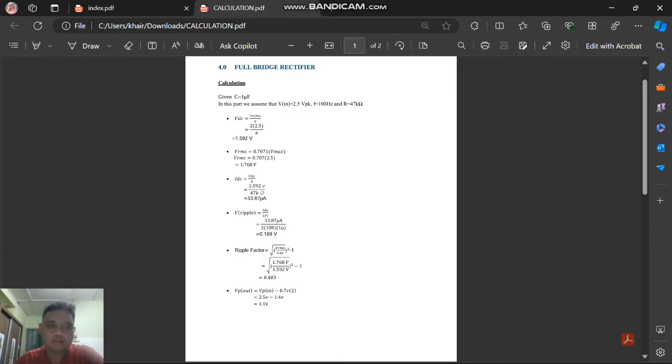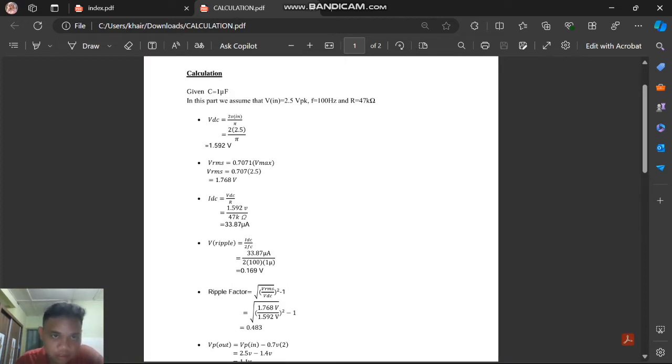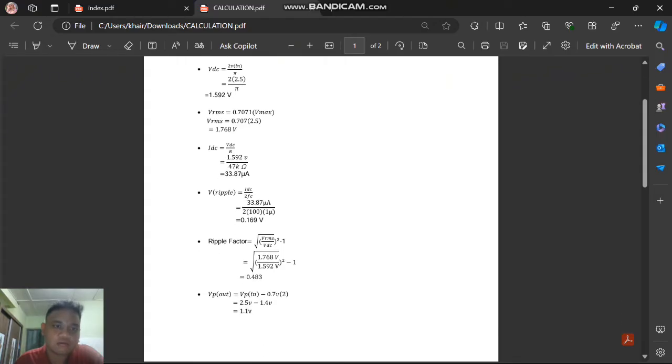To get VDC, we use 2 Vin over pi, and we get 1.592 volt. To calculate VRMS, 0.707 multiplied by 2.5 gives VRMS 1.768 volt.